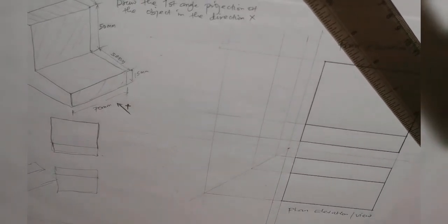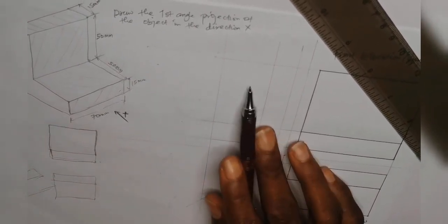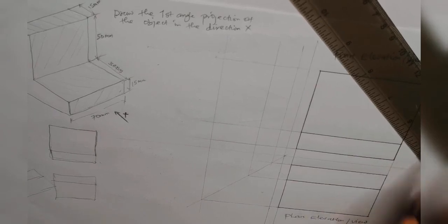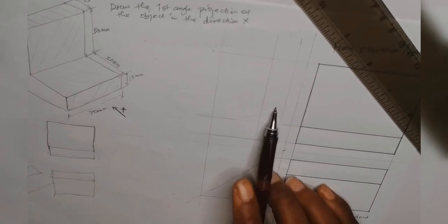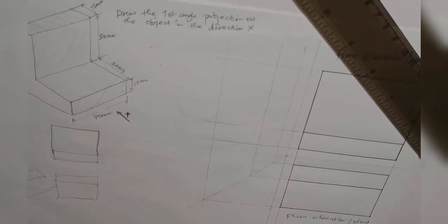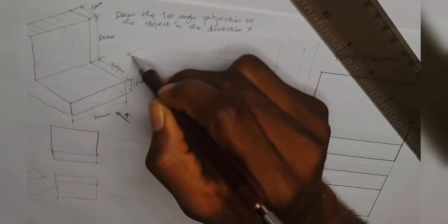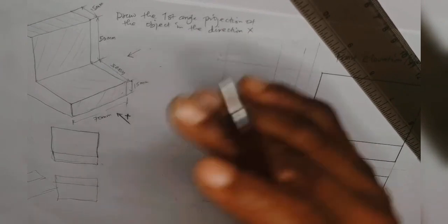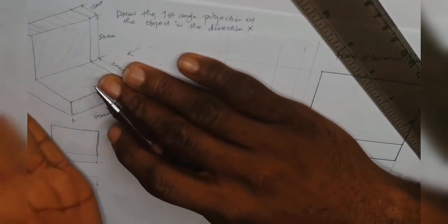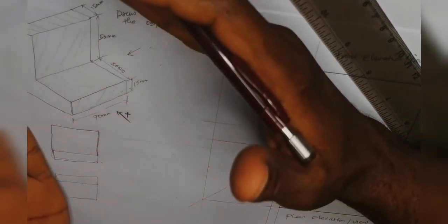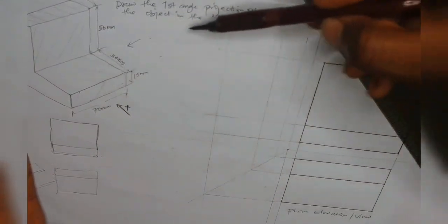Now remember I told you that at this point we'll draw the right hand side view, while at this other side we'll draw the left hand side view. So now, since we are drawing the right hand side view, this image is meant to be looked in this other direction, since it's the right hand side view. Remember, if I'm facing like this, automatically this side will be my left hand side and this side will be my right hand side, meaning I'll be looking at this image in this direction.